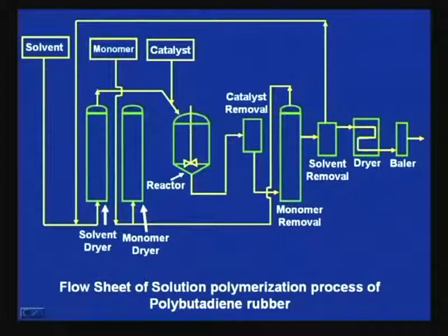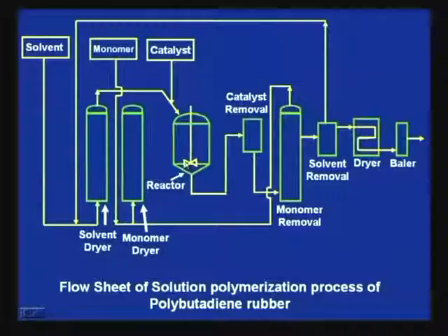Here this schematic of a stirring unit is required for homogenization of the mass in a solution polymerization for proper heat transfer, and details are not shown over here. It can have jacketed cooling or cooling coil inside. Inside there may be baffles, all those things. Then the monomer is converted to polymer containing the catalyst, say sodium amide or other catalysts used for polymerization.